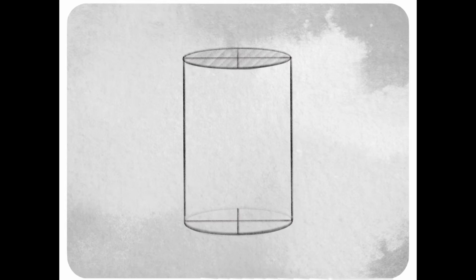The other thing that's important to keep in mind in the structure of a cylinder is that as we turn that circle of the top into perspective and we see that elliptical shape of the top and bottom, if you're struggling with getting the shape of that right, this can be a really excellent way to adjust that. You draw a cross line vertically and horizontally through that cylinder, through the ellipse, and then you check to see if each of those quarters in those divided areas match. If they're roughly the same, pretty close, then you know that you've reasonably well constructed that elliptical shape.